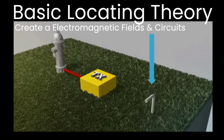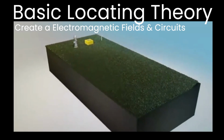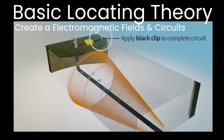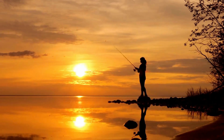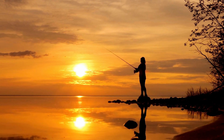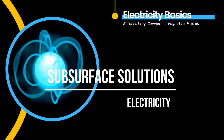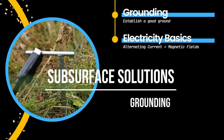But that's passive locating. Active locating is actually setting up a transmitter, putting a ground rod in the ground, applying your own frequency, identifiable frequency, that's not going to interfere with other frequencies that are in the atmosphere, and we're able to receive it. The next session, we'll talk about your rods. We'll talk about your ground rods. We'll go from electricity basics to how to apply that electricity. How to ground your system is very important.